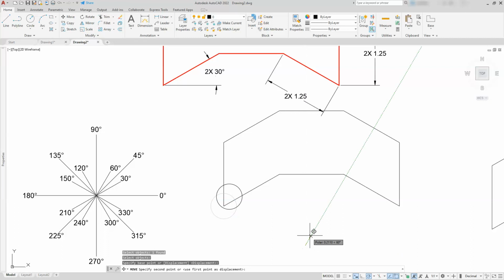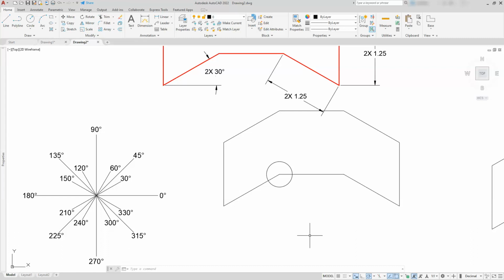And next I'm going to do the angle syntax just like we did before. So my dynamic input is still turned on, 1.25, angle, and then I will type in 30. And if I do that correctly, you will want to see that that's going to move that center or that circle from its center to that other center, just because I know the distance that it is going.